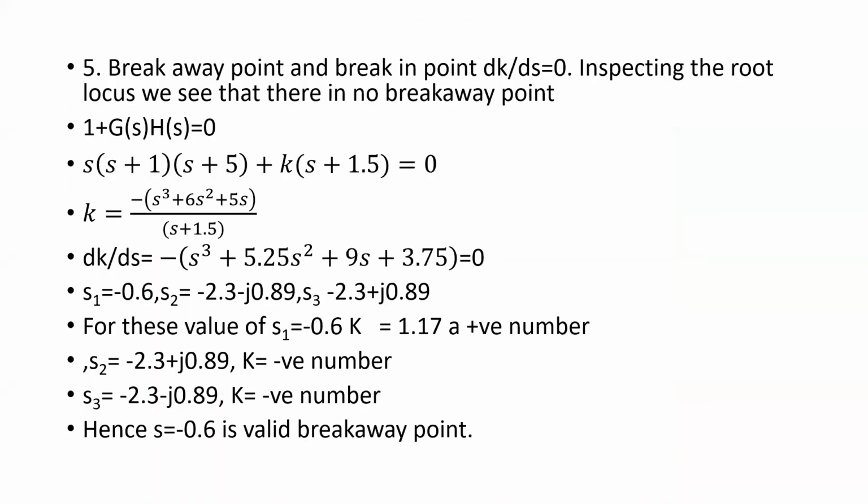Then we have to find the breakaway point. As it is S cube, you will have three breakaway points. We will have to check. Here the K value is positive, so this is a valid breakaway point, whereas the other two are not valid. You can check using the angle criteria also.